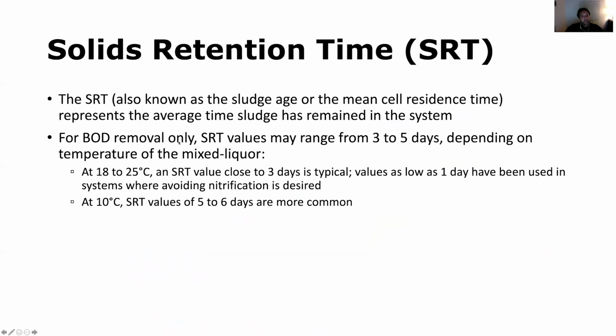All right, for BOD removal only, typical SRT values may range from 3 to 5 days, depending on the temperature of the mixed liquor. So at like 18 to 25 degrees, an SRT value close to 3 days is typical, but you'll see values as low as 1 day used in some systems, especially when the operator does not want nitrification to take place. At colder temperatures, you might see SRT values more like 5 or 6 days.